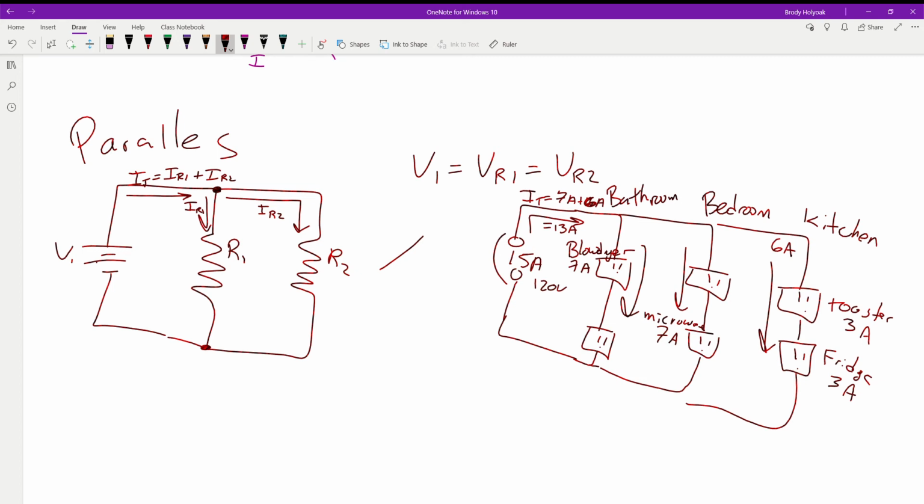I'm like, one room per plugs. We have 1 room that's plugs, 1 room that's lights. Plugs and lights, 2 breakers, because it just makes things a lot easier when you're trying to fix stuff. Also, the big thing is when you're working on circuits like this, always shut the breaker off. If you don't, you will get bit.